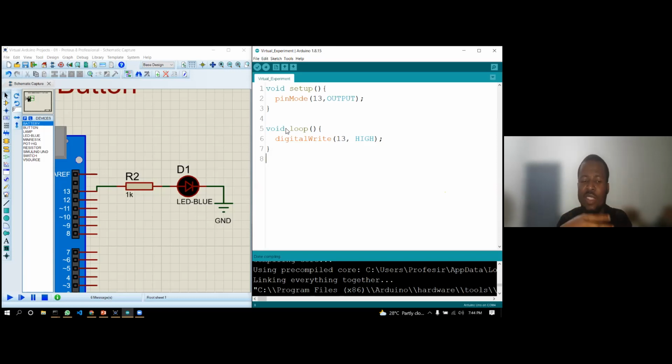Okay, the hex file is, in other words, the machine language version of the code that we've written. What I have done has actually linked, and since I've linked this to my Arduino already, the connection is already there. So now let's see if I run this simulation, you see that the light turns on. Ladies and gentlemen, this is your first Hello World application on the Arduino platform. Any questions up to this point?